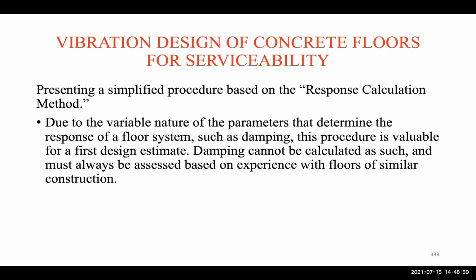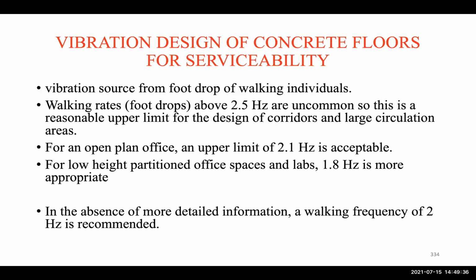Here we can determine the response of the floor, and we can have an estimate of the damping, and an initial estimate of the vibration, and then based on the criteria that we have, this will tell us what we need to do in terms of adding stiffness, and in terms of adding mass, etc. Okay.